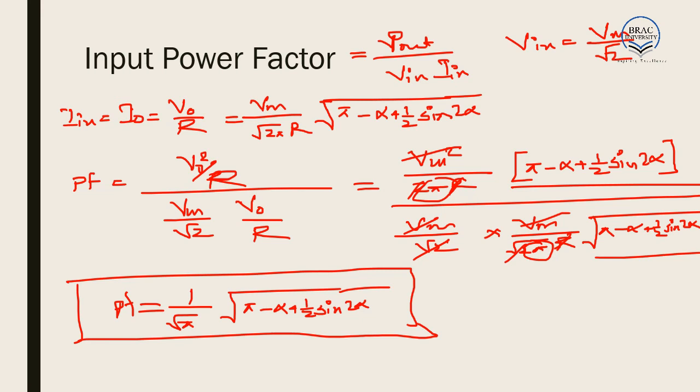That is, the input power factor is the best when we are not using the AC/AC controller. So we can use an AC/AC voltage controller to get an AC voltage output with a decreased magnitude, but we do this at the expense of deteriorating the power factor. There is always a trade-off involved.